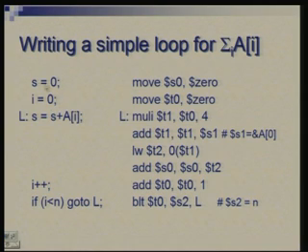These steps are implemented by very straightforward move instructions, where you move 0 value into some register. So, now remember the correlation between the variables and the registers we are using. We are using S0 register for holding the value of sum. We are going to use T0 register to hold the value of the index. Now, here we have written a single statement S equal to S plus A[I], but this needs to be broken down into a number of steps.